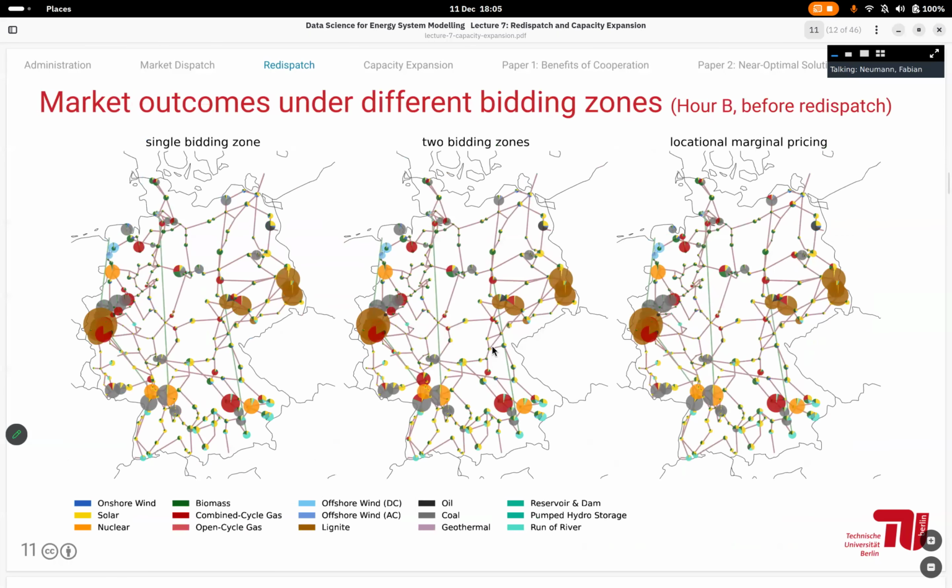They do a cost-benefit analysis: what would be the welfare in the system if this line is there, and what is it if the line is not there. Then based on the level of value, the transmission system operators or the project developers can apply for funding and subsidies for these projects, especially if they are of a cross-country interconnector kind.